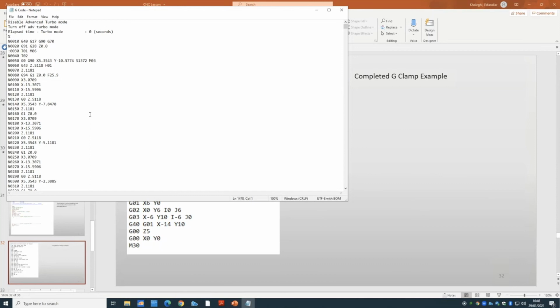Knowing that will give you much more information about the post-processing basically, and you can realize how useful CAM was for you. Even these days, although they trust NX, if you define something incorrectly, for instance, if making a zero was incorrect, the rest of the code is incorrect. All these 4,000 lines are wrong, because the moves you have are not right. So doing those sorts of setup is really important.